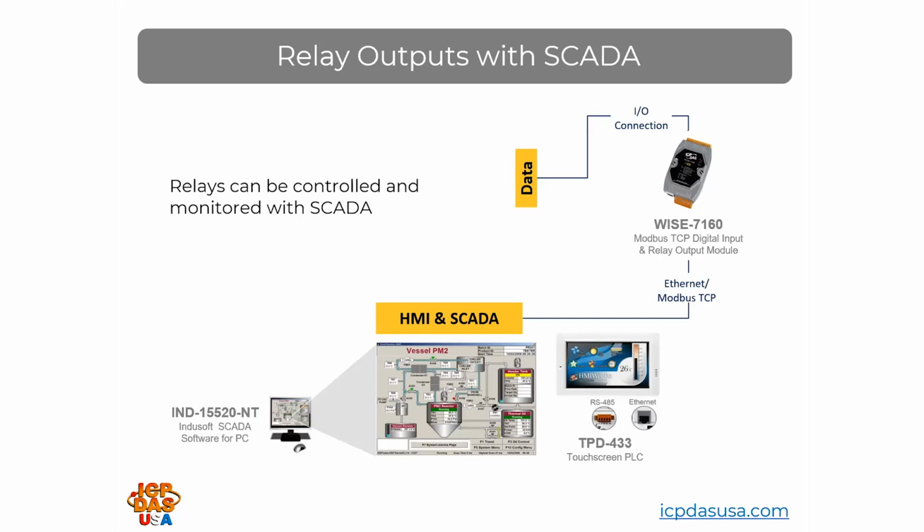These WISE 7160, they allow for setting up if-then-else type logic rules through web browsers. They communicate over Modbus TCP, so they're also being used with TPD 433 touchscreen PLCs that communicate over Modbus TCP, and they're being used for monitoring and control.